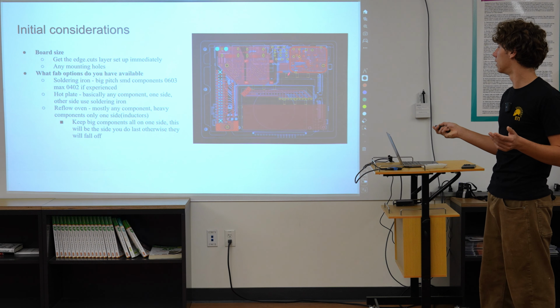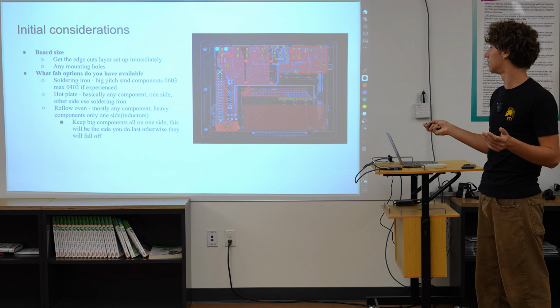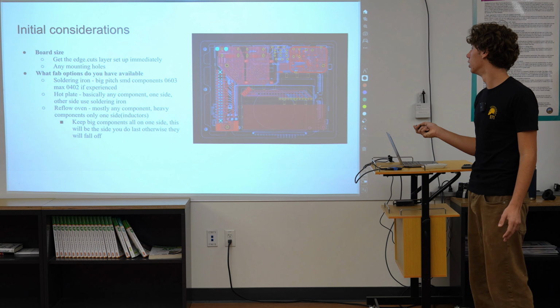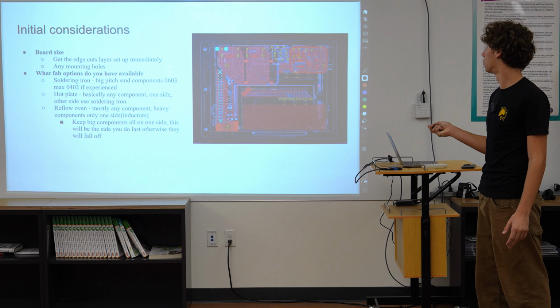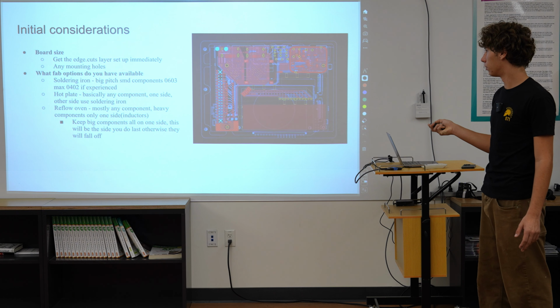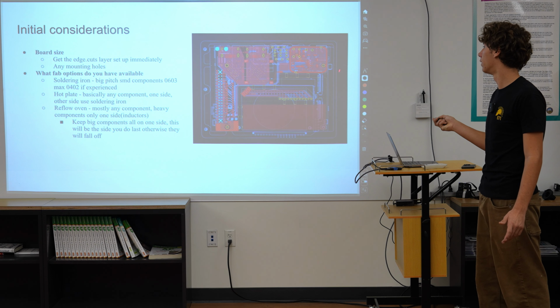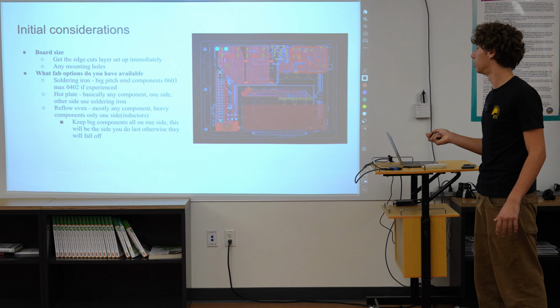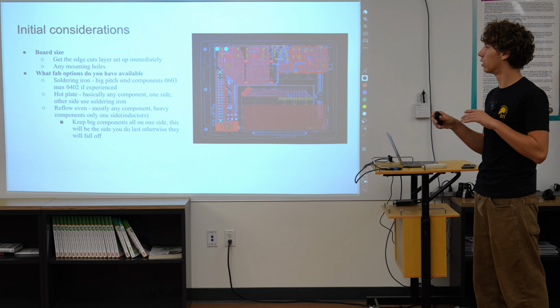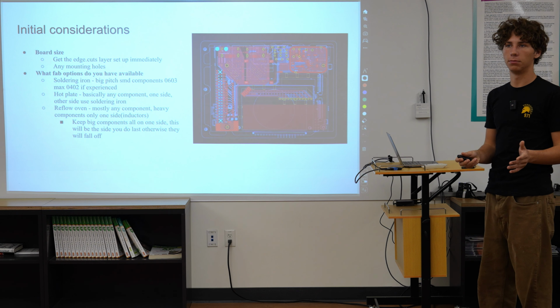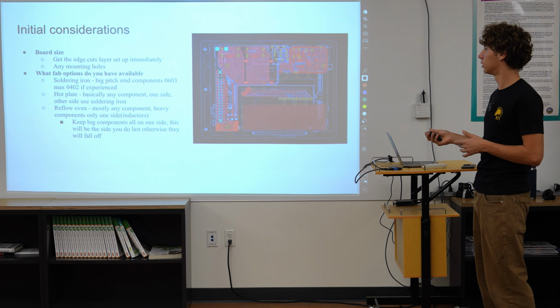For example, like this right here, there was no constraint making this line right here where it is, but we wanted enough space for the ribbon cables coming out of here to go into here. So, you know, if you need just a little bit of extra space, obviously you can move it out, or if you don't need it, you can move it back in. But just having the opportunity to visualize where all your components need to be based on what the outline of your board is going to be really important in your design process.